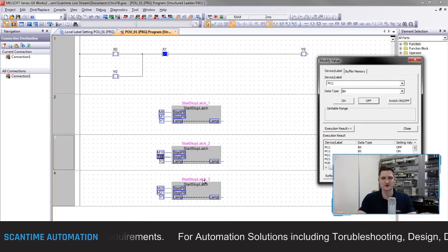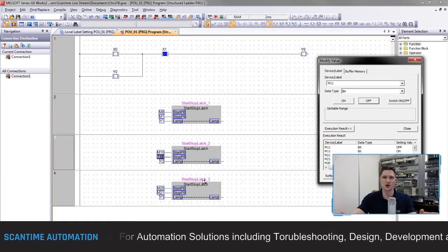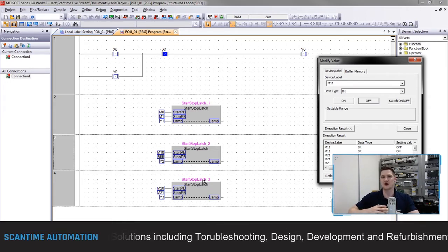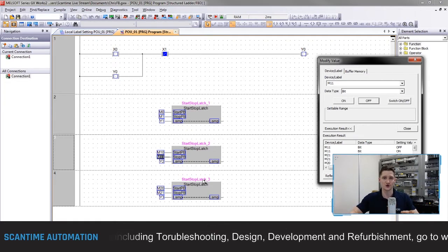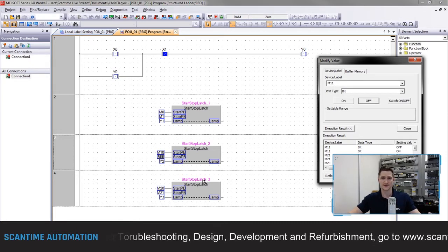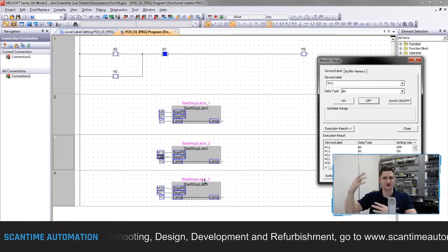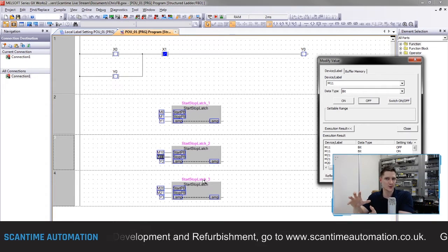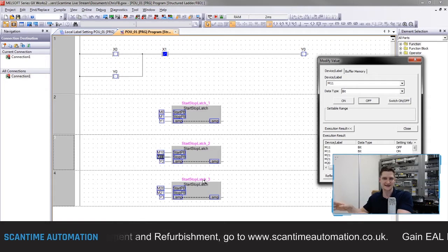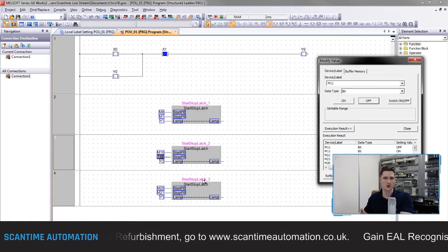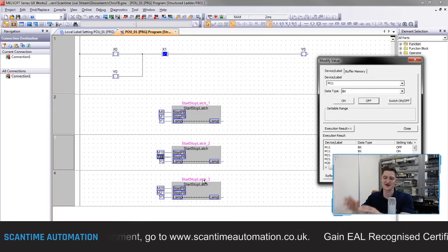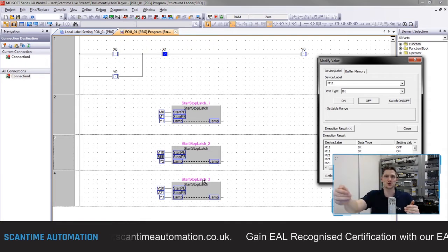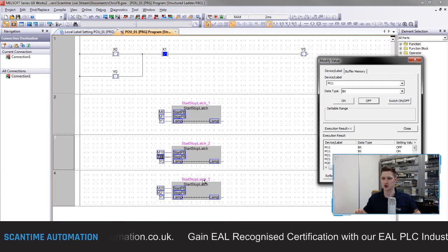As I mentioned, it's not too difficult when you've just got one network, which is just 3 contacts and a coil. But if you've got a program, let's say that's controlling a conveyor, and that program is 10 networks long, and on the shop floor you've got 10 conveyors. Instead of having to rewrite those 10 networks 10 more times, giving you 100 networks in total, all you do is take those 10 networks that control that one conveyor, place them inside of a function block, address it all up inside of the function block using its local labels, and then use that function block 10 times in the program, addressed to the individual addresses of each conveyor. And that's it, job's done.